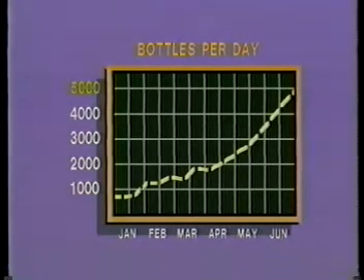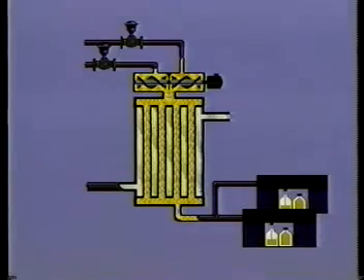This was the general plan for the new process. Raw materials would flow into the top, and their rate of flow would be accurately controlled. A motor-driven agitator would provide rough blending of the raw materials, but for the final blending, the product would flow through a heat exchanger where it would be heated to 80 degrees.